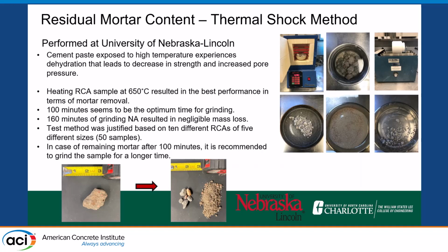Obviously, that mortar content is going to drive water demand if you're trying to use it in new concrete. That also tends to be the part that abrades off if you're using RCA in unbound uses. And so it's always of interest to see what the residual mortar content is on RCA.